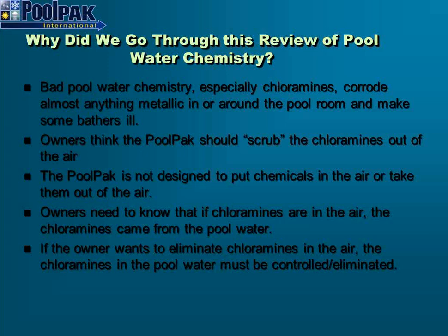But if we don't have proper pool water chemistry, then the PoolPak unit will not be able to do anything about that, and we could cause damage to the structure due to corrosion. It could create an atmosphere that's just not good for swimmers and other people using the pool, including spectators, and they're just not going to have a pleasant environment to swim in and to watch the swimmers.